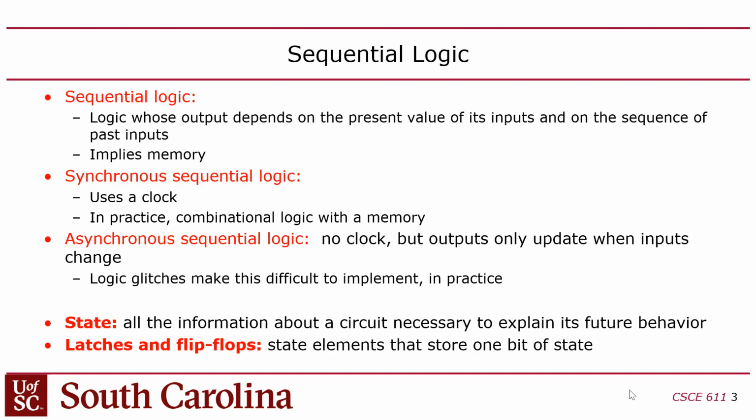So you could technically have sequential logic without a clock, asynchronous sequential logic, but no one's ever really gotten that to work, unfortunately. It would be great if it worked because the clock consumes a lot of power in chips, because the clock is distributed all over the chip. So if you could come up with a practical way to build sequential logic without a clock, that would be a $1 billion idea, because that would make chips consume much less power. But the much easier way to do it is with a clock. So basically, you've got a clock that's synchronizing all the sequential logic.